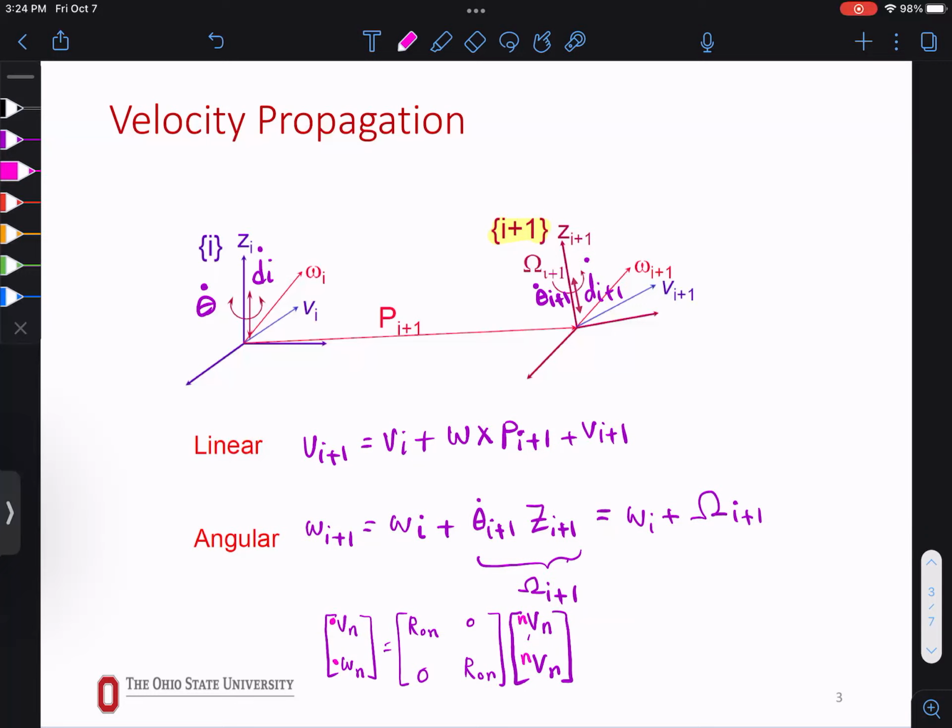So when you're designing your robot, you don't have to use all the same actuator. Your last one probably can use a weaker actuator than your first one. The first one has to tolerate all the torques. Does that make sense? That's why we need to know this. But you don't need to have this relation for all of them. You just have a general torque. You find it with respect to the baseline, and then you can walk and convert them.